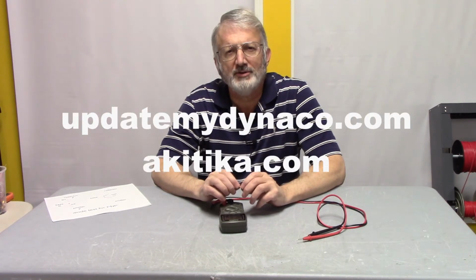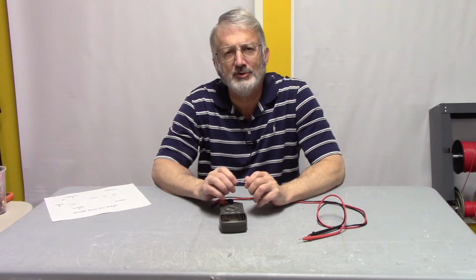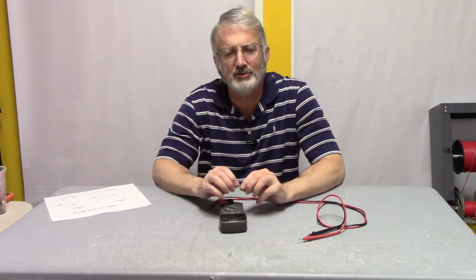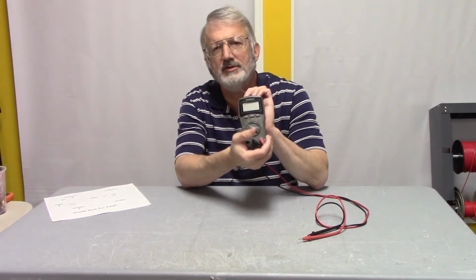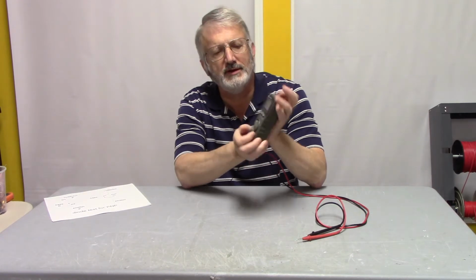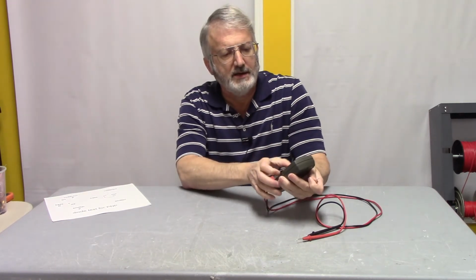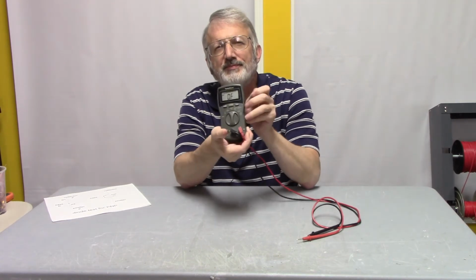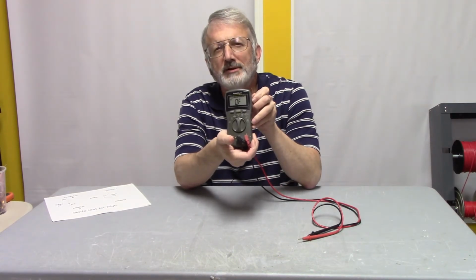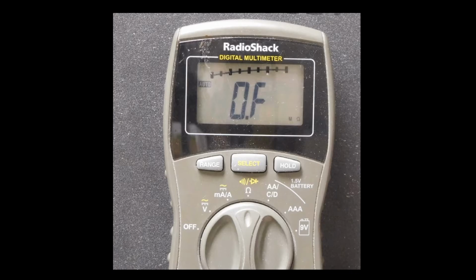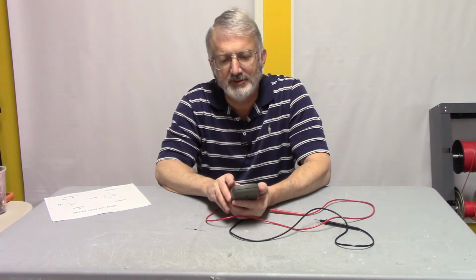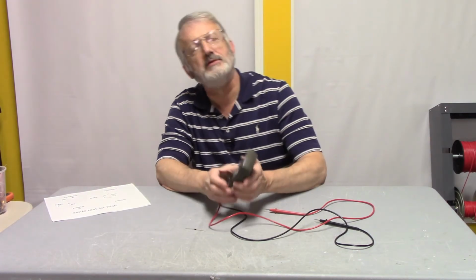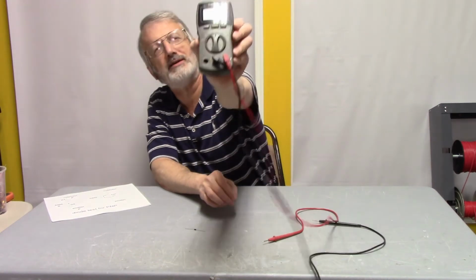A question I often receive is how do you check diodes and transistors to make sure that they're grossly functional? That's what we're going to go over today. So what I've got is a standard Radio Shack meter, nothing very fancy. It has an ohms range, and we can zoom in on that a bit. There's a select button on this meter, and we'll hit it 2 times until we get the display that shows the diode on the right side of the display.